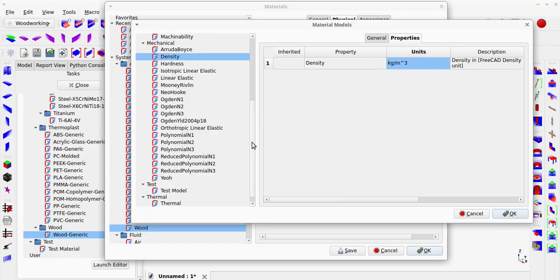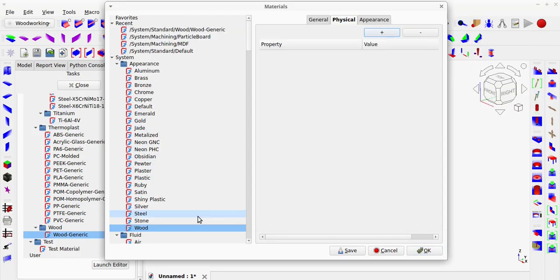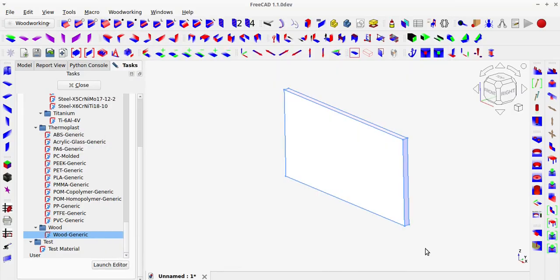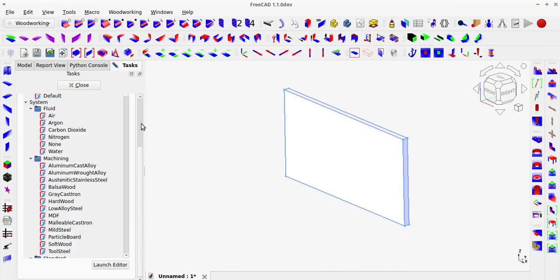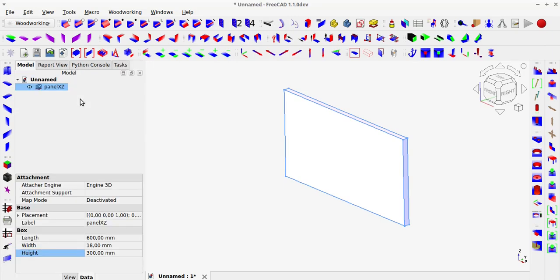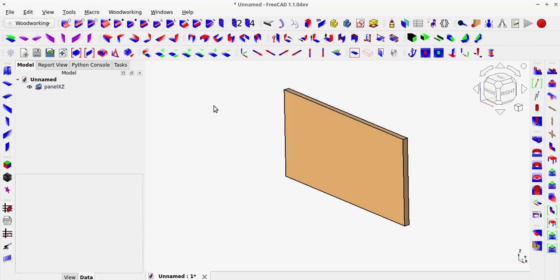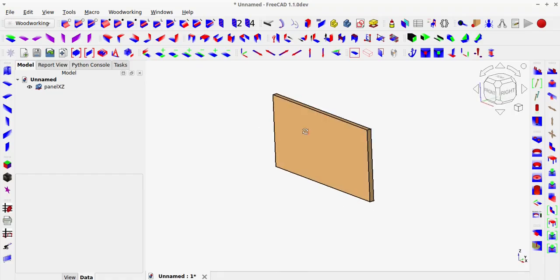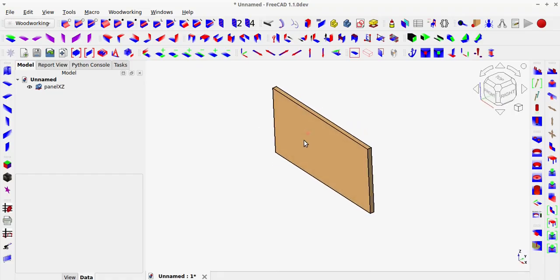I personally weighed a 342 mm by 860 mm shelf and found it weighed exactly 4 kilograms, which translates to 13.6 kilograms per square meter. The shelf is 18 mm thick and made of laminated chipboard, but it came from an old wardrobe from many years ago, which suggests that chipboards were much heavier in the past. So the density does not work here. So it is best to weigh and measure a sample of the wood you are working with. The larger the sample, the greater the accuracy.